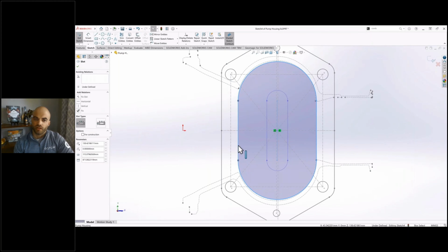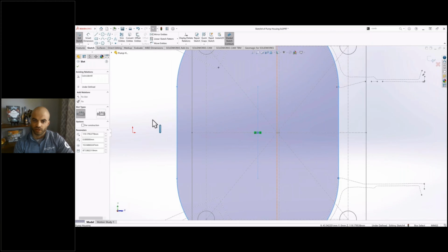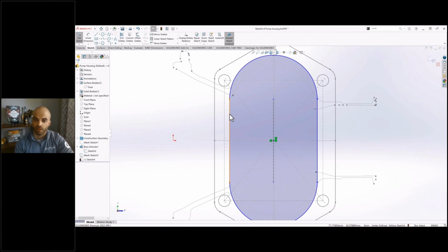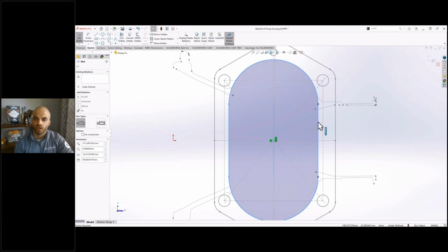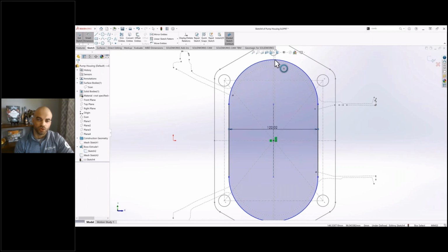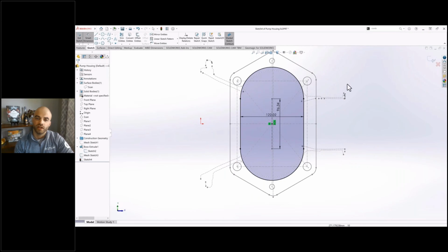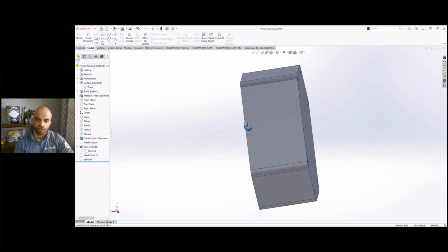You'll notice in that other sketch, I didn't center everything. That's another thing that I've learned that can sometimes come to bite you in the butt. If you make too many assumptions like that without knowing what you're doing, you can potentially cause some issues later on where things are supposed to be collinear and they're off by 0.1 millimeters, and then you get a weird surface and it takes a second to go dig and find it. It's not the end of the world by any means, but it's just lessons I've learned as going through and doing a ton of these things.